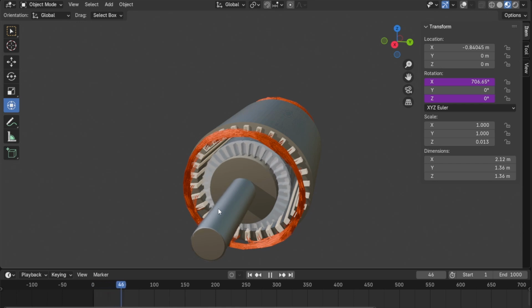Anytime you have a bad connection or undersized wire, it's going to heat up. And anytime you're using electrical energy to heat something up, you're going to have a drop in voltage. You're loading it down. And so that means that the effective voltage seen by this motor, by the stator windings, is going to be less than it's designed for.